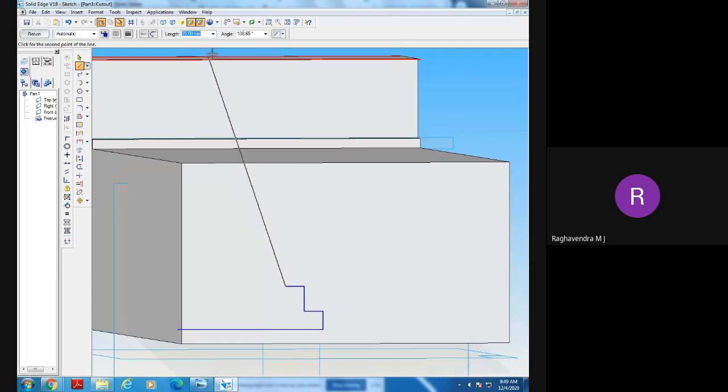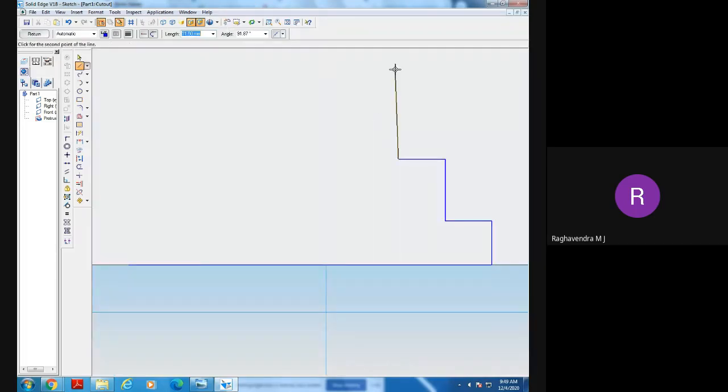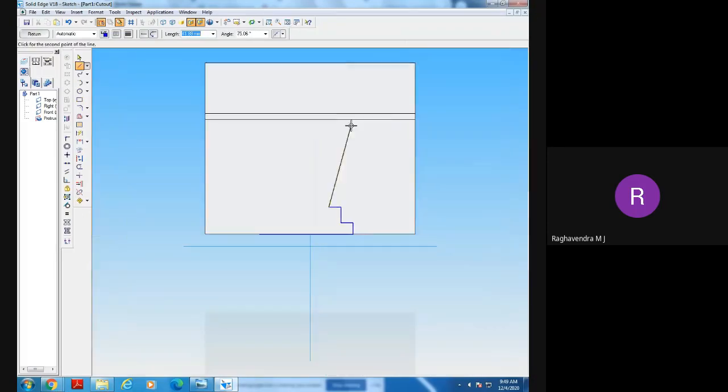Click on the sketch view. It will come to sketch view. Once again, fit it up to this. Up to this you come in this direction. Once again, come down. Once again, you move the cursor, and it will show the alignment indicator. End it.